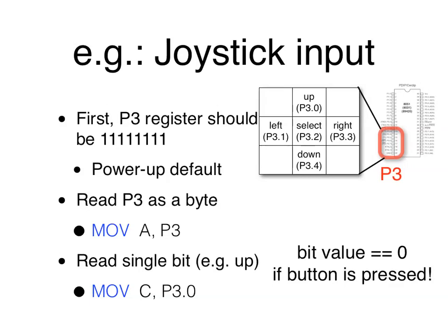Okay, so I'm gonna continue with general purpose I/O ports, and this is, I think, where we stopped last time. Last time we looked at outputting using LEDs, 7-segment LEDs. Well, now general purpose I/O ports could also be used for input as well. It's those same pins that you can connect to hardware for both input and output purposes. This is showing an example of using it as input.